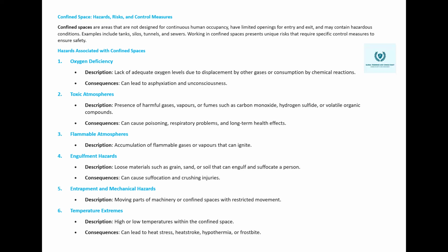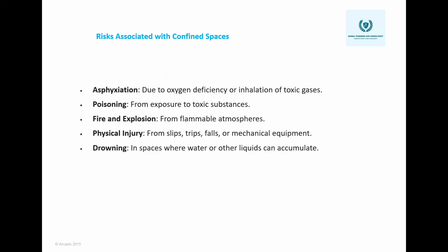Then we have entrapment or mechanical hazards. We are using machines, plants, equipment, so we can get entrapped with that, like our loose clothing, body parts, or parts of jewelry can come in contact with the rotating parts or the moving equipment, and that is a major hazard. Then extreme high or low temperature is one of the hazards, as well as excavation.